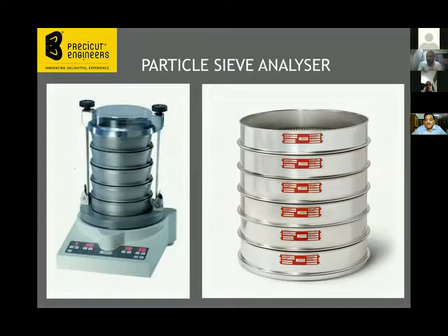So for example, for 0.6 to 0.7 mm, the standards might say that 5% by weight, the shot should be in the range of above 0.6 and below 0.7 mm. Then the next stage they will say is that 80% shot should be in the range of 0.55 to 0.6 mm, and so on. They'll define the percentage by weight. So first thing is you have to analyze the shots, see that they follow this particular pattern in terms of size distribution. If okay, then we'll go to the next stage.